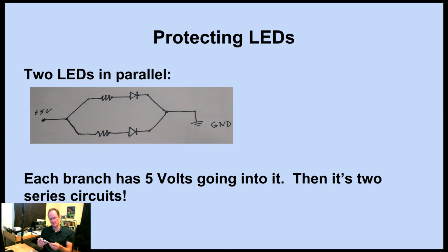But what you can do is take the nearest value. If you have too low of a resistance, if you take the nearest value down, you do risk damaging your LEDs. As long as you're close, you're probably okay for these types of projects that we'll do, but in general, you'll want to do the next value up, even if it means it's not quite as bright as it would have been otherwise.